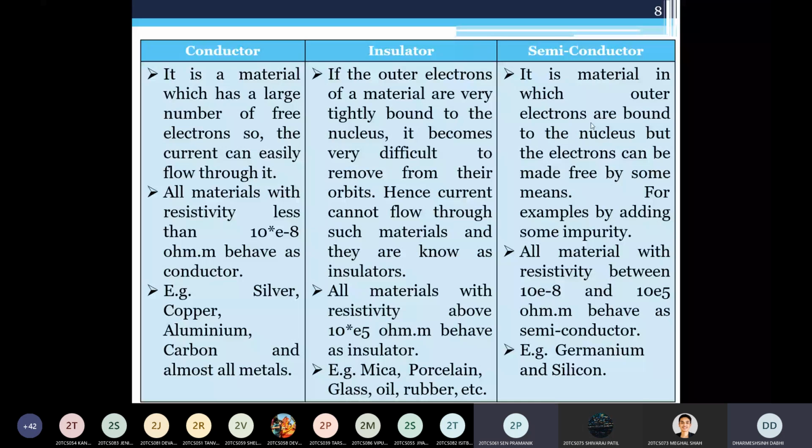If a diode is made of silicon material, then you require a threshold of 0.7 volt. Clear? If it is germanium material, then you require 0.3 volt. It means you require some threshold voltage across the two terminals of the diode. After that, current will start flowing. Clear?